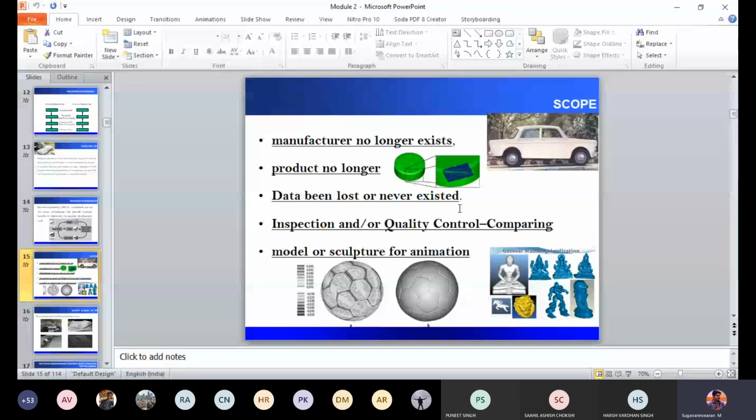You have a component which is designed in a CAD model, and the component is fabricated using some manufacturing process, right? After manufacturing, using a reverse engineering process, you measure the data and merge the measured data with the CAD data, because CAD data is a perfect dimension. You may not consider any environmental issue or machine malfunction in CAD. If you want a diameter of 10.0378, it is feasible in CAD. But manufacturing exactly 10.0378 is not feasible in a manufacturing process, because there are a lot of other issues associated with physical manufacturing. So there might be some tolerance variation.